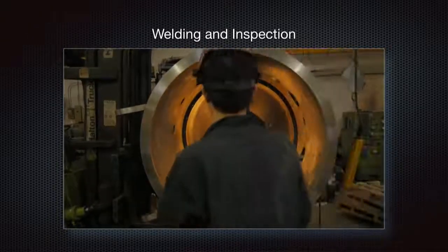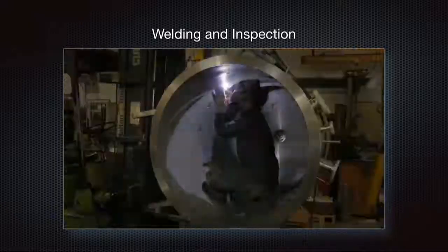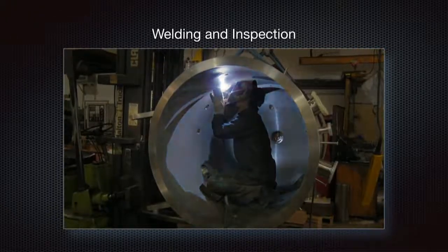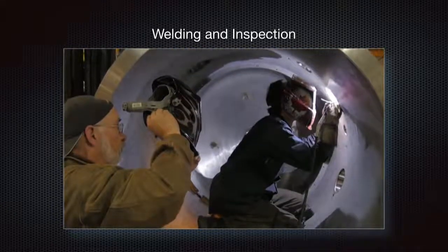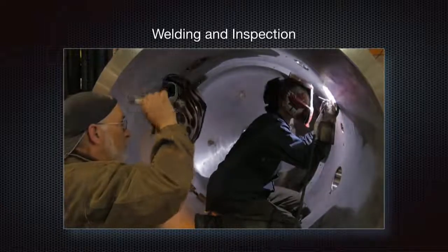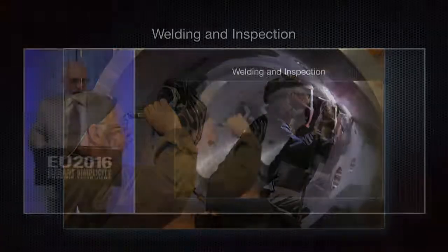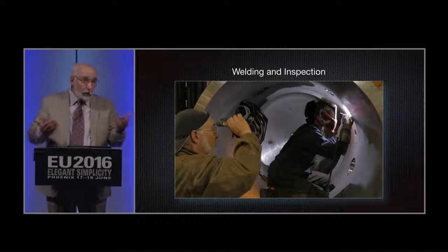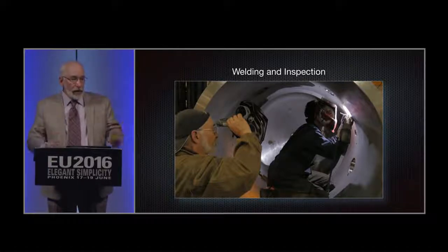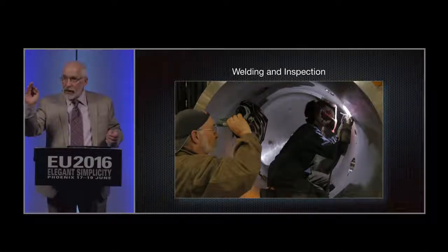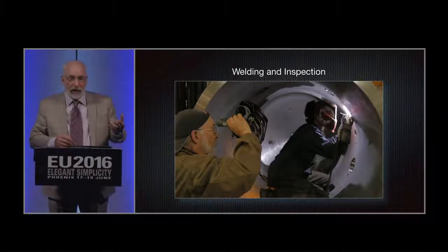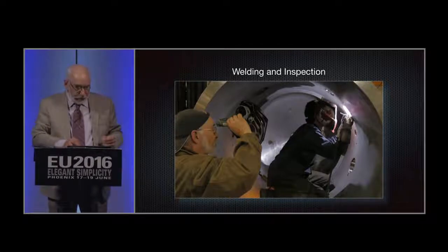If you have one pinhole, you no longer have a stable vacuum in your chamber. Normally when you build a machine that's complex, you're going to have vacuum leaks, and we do at this stage. We've got some work to do. We may have to discover that there's a pinhole someplace in one of these welds, and we'll have to come back and plug that weld.